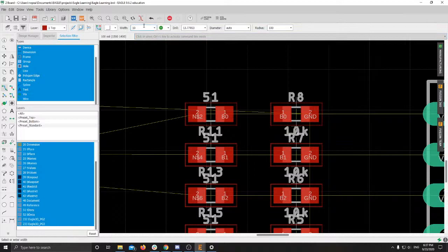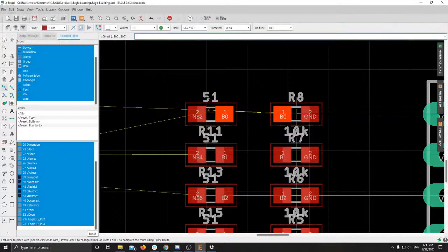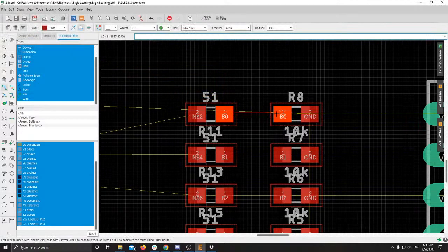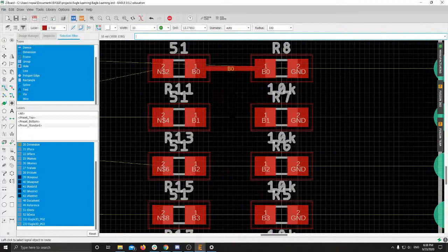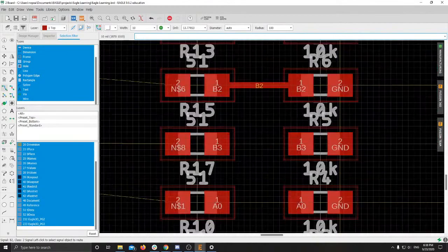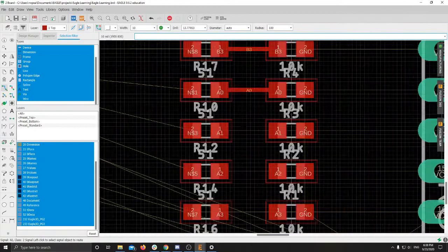That's your width up here. That's how you set it. And then make sure you're in the top layer. And then I'm just going to click here, route it over. Oh, this is one thing. You do want a smaller grid for this. The grid size here affects where you can actually do bends. You'll see right now I can only do it on these areas. But I might want a finer resolution. So that's where I'm going to use 10 mil. So I'm going to come over here, connect like that. And then I'm just going to do that for each of these resistors, and we'll move on to something else next. If your resistors are in a similar spot, hopefully you'll have something that works out nicely like that.